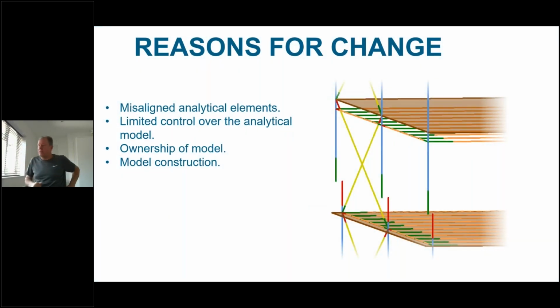So why are we changing this? Well, one of the things that we had a problem with here is that how we generally construct a building isn't necessarily how you would analyze it from a structural point of view. So we've got an example here on screen. You can see that we have a floor plate and all of the steelwork that's actually supporting that composite deck is actually below the floor. So of course that's how it's built, but not necessarily how we want to analyze that.